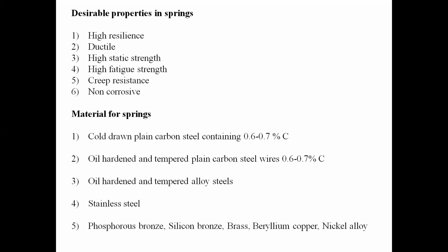So the list of different materials is in front of you. As the resilience property has to be achieved, we need to cold draw or harden the spring. Very important. Here you can say cold drawn plain carbon steel containing 0.6 to 0.7% carbon. Or the second material, oil hardened and tempered plain carbon steel.